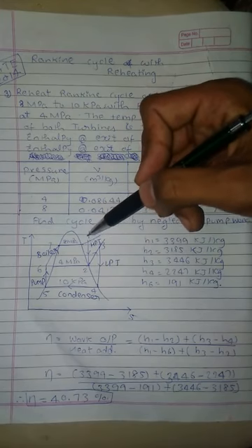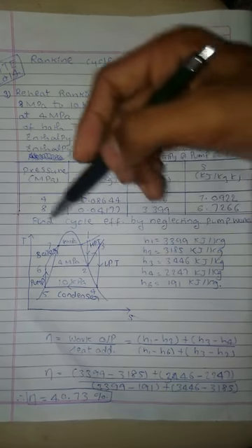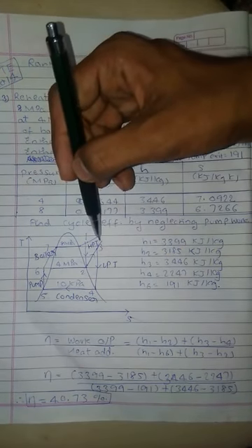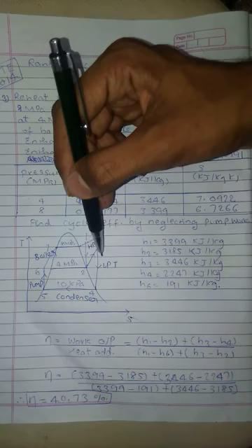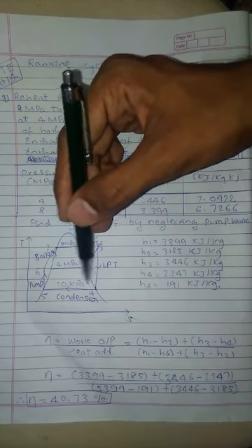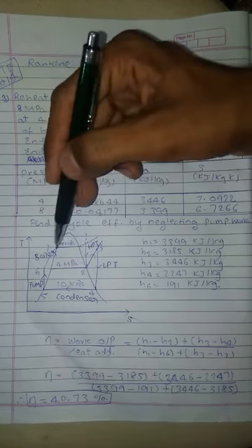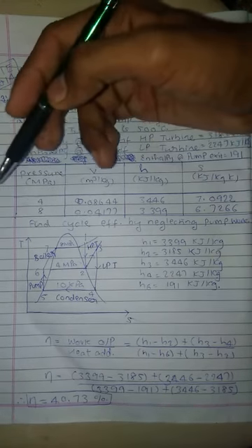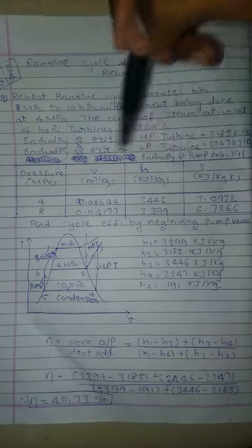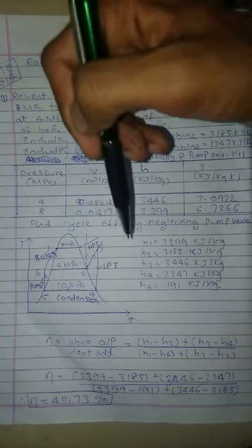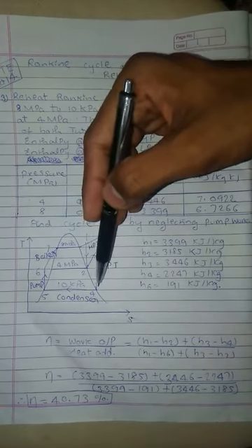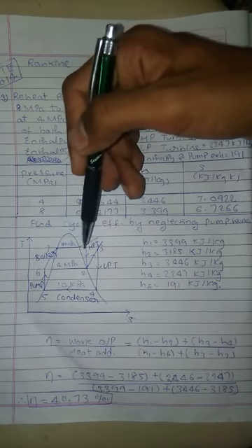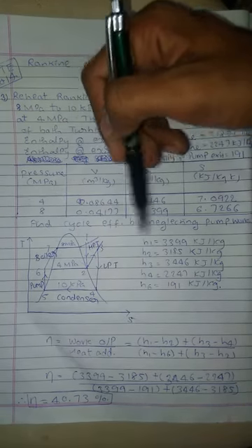So before going to condenser, first it will go to reheater where the steam will be reheated, and then again expand in the LP turbine, and then into the condenser, then pump and boiler. Okay, now here all the values at all states are given, so no need to worry about the state of steam at point 2, point 3 or point 4. Every value of enthalpy is given in the example, and you have to find out only the